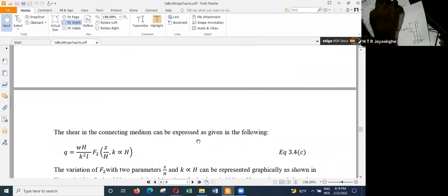Yeah, so any questions, chats, anything you have? Oh, I have 11 chats. Let's see. One question: provide diagonal bars about the core wall openings. What is that core wall? Yes, core wall openings. You have to provide these diagonal bars when you have core wall openings.